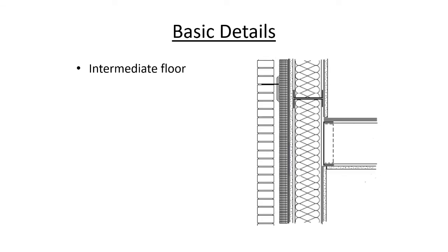On an intermediate floor basis, we can see that the floor system is tied in to the balloon framing. We break the steel stud framing just above the floor line. The cavity of the studs is filled with insulation. Again, gypsum board on the inside, gyp sheathing on the exterior side with a WRB air barrier, continuous insulation, brick ties, and then the brick itself.